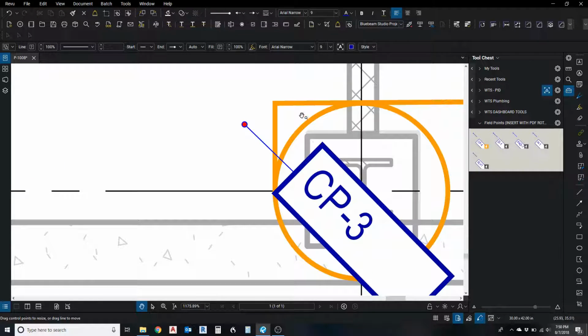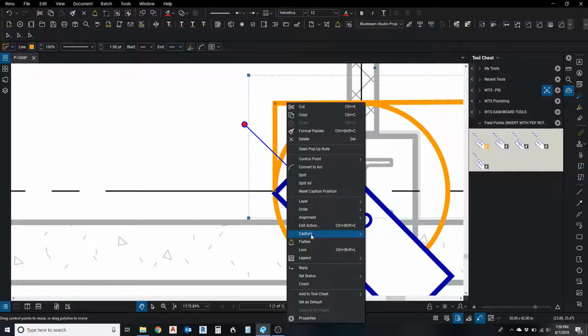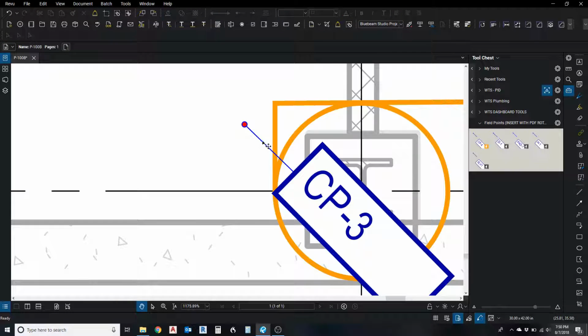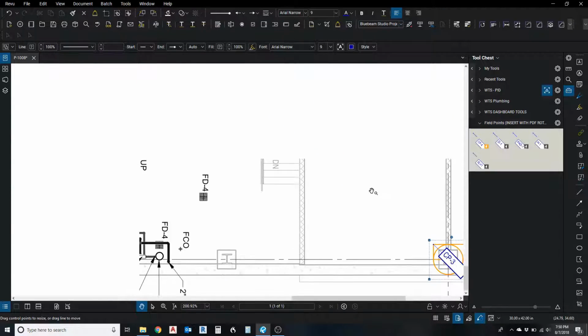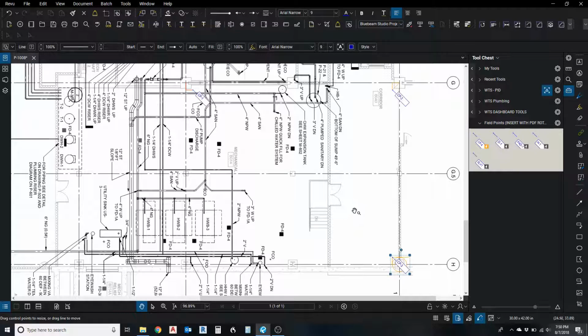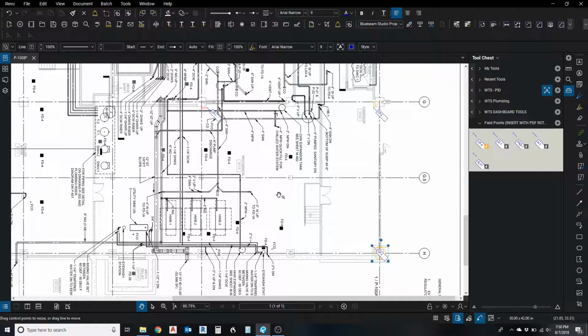That geometry is really important. The Trimble is going to say that it's bad control if you don't get that geometry right. I'm going to flatten this one. Boom, flatten, and move up there, there. And those lines were all ones that were 2 feet by 2 feet off the columns. So I'm just putting in 3 control points for this because it's just a tutorial. But after I have those 3 control points in, I have control over this area, all right?